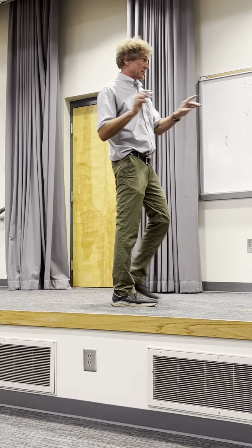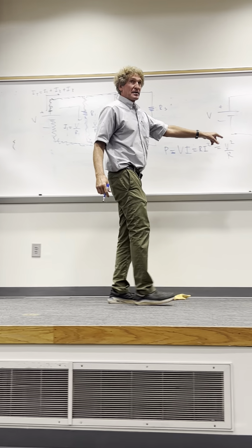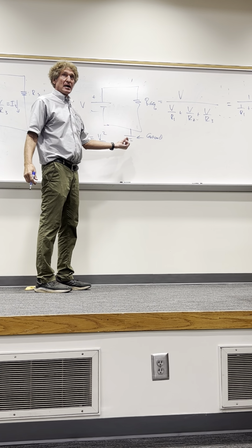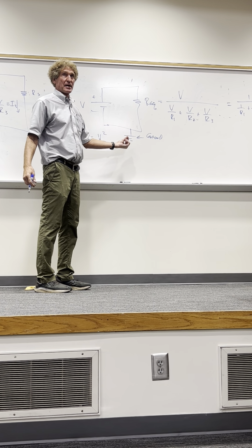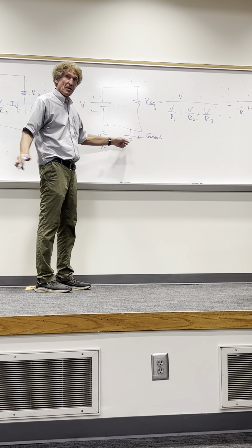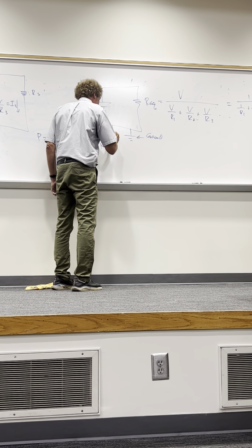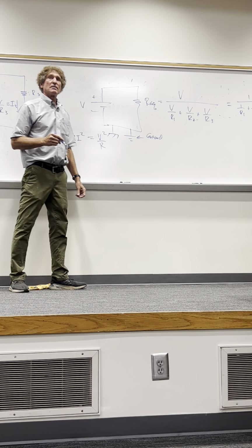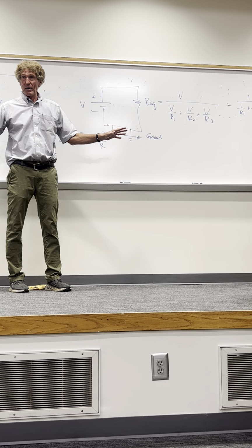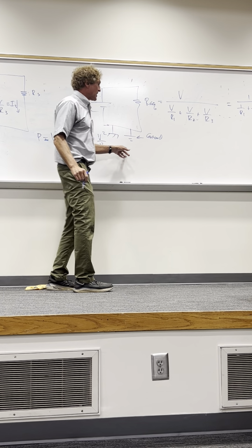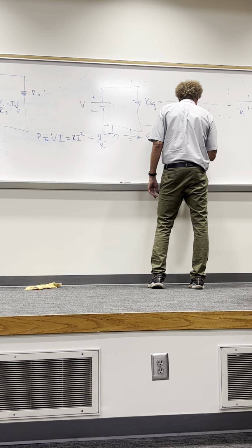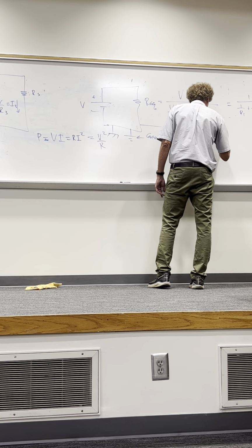Now, some of this when I'm showing you here, this 3-line thing with progressively shorter lines, that's really called a chassis ground. And then there's something called a signal ground. I'm not going to differentiate that. Anytime you see this symbol or this symbol, they will appear like this. One of them's chassis, the other is signal ground. Don't worry about it. They're the same to you. All right? There's no problem there. But if you see this symbol, that is an earth ground.